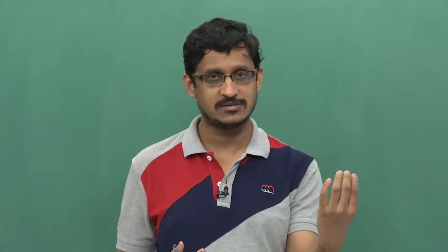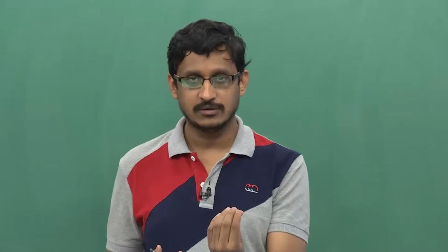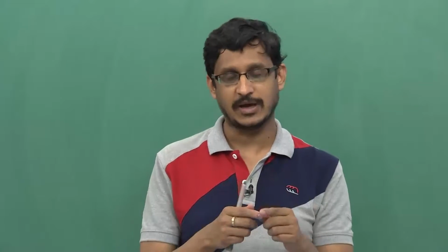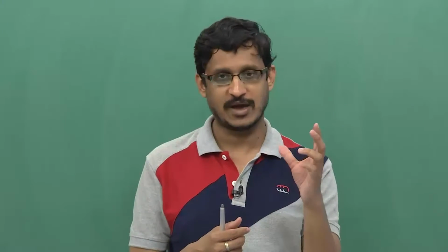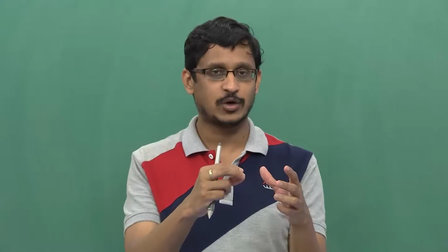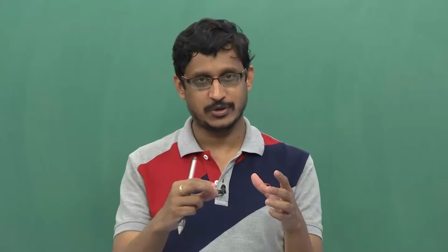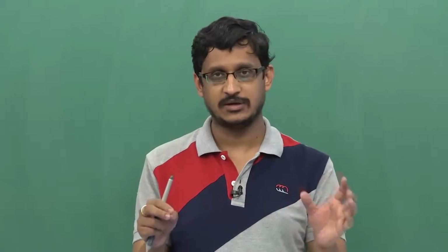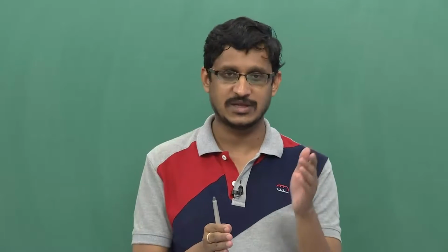So, there has to be a laser to fiber coupler. Sometimes this comes with a package. You have a laser diode emitting light, there is a micro lens which focuses light onto a pigtail of the fiber. We call this a fiber pigtail, which then completes the laser diode. That is to say, the optical source comes with a laser diode, a lens and a fiber.